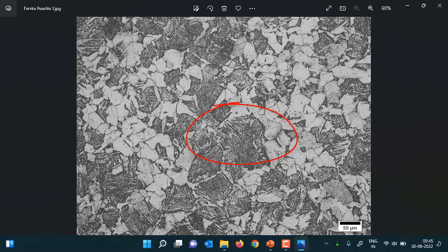The black phase followed by a white region and then again a black lamellae and so on. Alternate layers of cementite and ferrite. Okay. So the black one is cementite, and in between two black lamellae, the white portion that you have is the ferrite. That is the eutectoid ferrite. But apart from that, you have a lot of these white grains, right? For example, here and here and here. Okay. So this is the pro-eutectoid alpha phase.